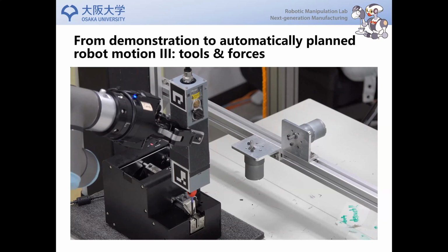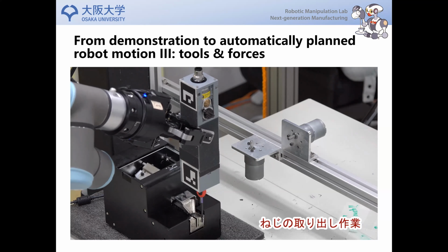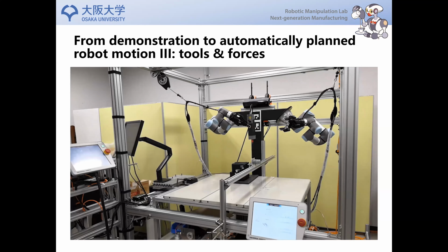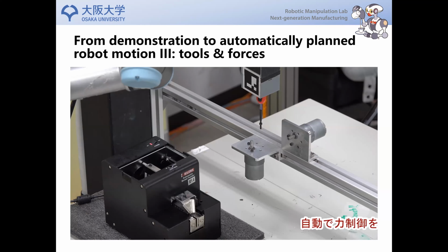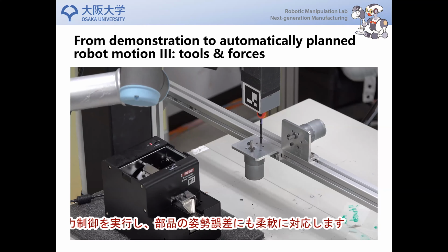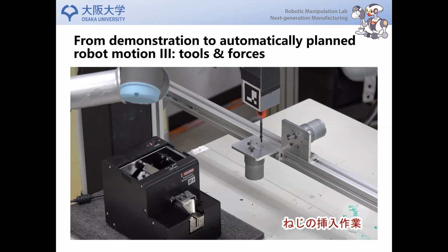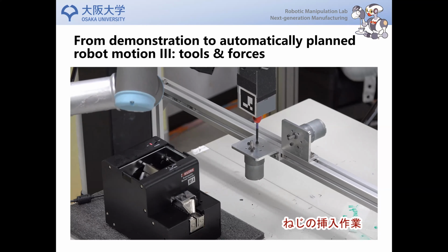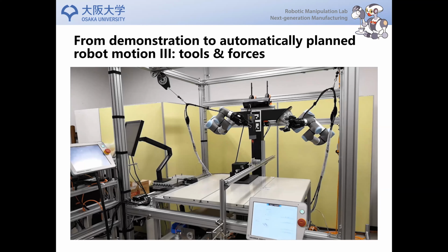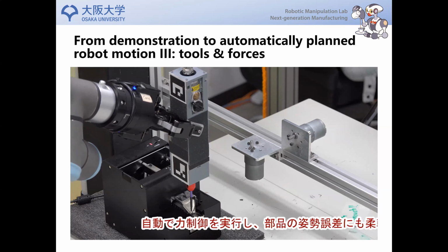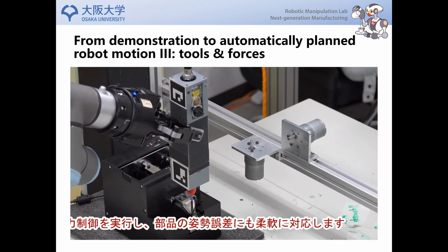During the execution, you have already seen that those bolts are very small, so the robot has to include some feedback. Here we are using a 6 degree of freedom FT sensor installed at the wrist. Also, here is a big difference from the hole. The robot is doing a spiral search and then impedance control to make sure the bolt is correctly inserted into the hole. After detecting that the bolt is correctly inserted in the hole, the robot is going to fasten it. And then it's going to pick the second bolt and move the tool to the second installation pose.